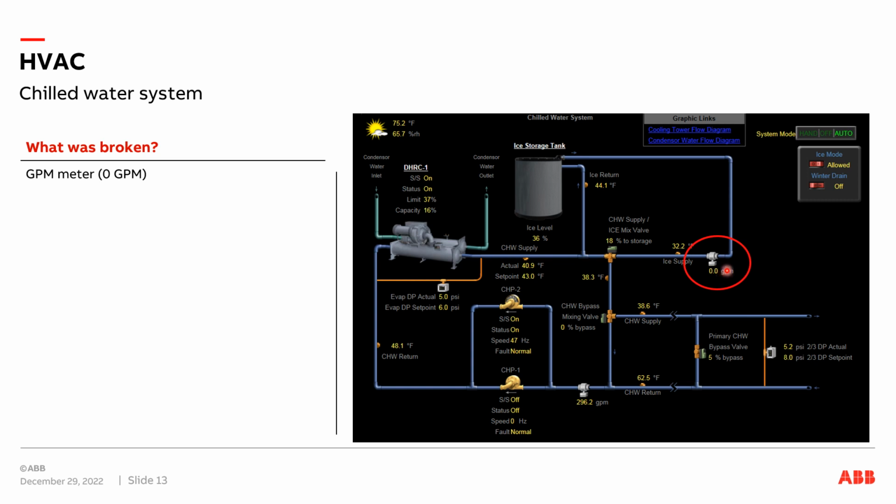So this tells me my meter right here is broken. This is something that, when I took these screenshots to create a presentation, I let our facilities folks know that we had a problem and they were able to get that fixed. Also, when you look at some of these temperatures and things like that, you have some tolerances with sensors, so don't worry if you see something that's off just a little bit. But when you see something that's off a lot, that's when you know there are other problems. So what's that other problem?